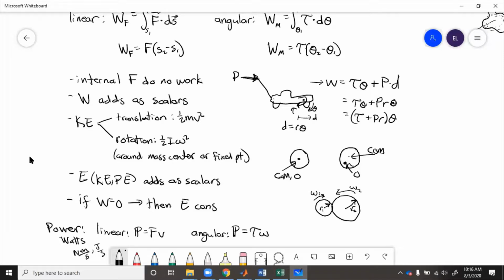So they need to make the motor stronger than it would normally be. So they amplify the torque using this gear train. We remember that V equals R1 omega 1 equals R2 omega 2. And V is constant at the tooth. So this would be V here.